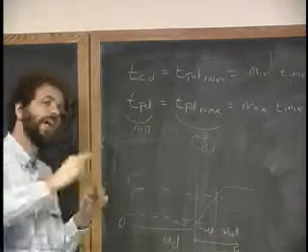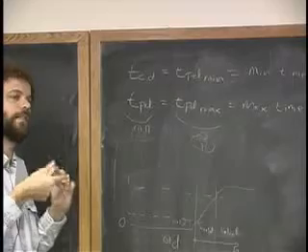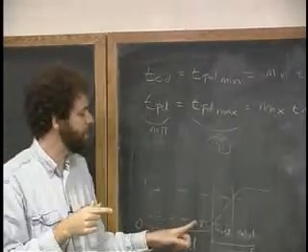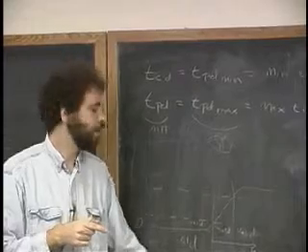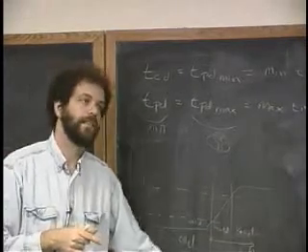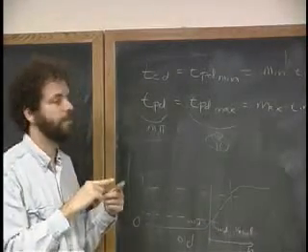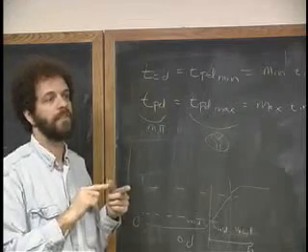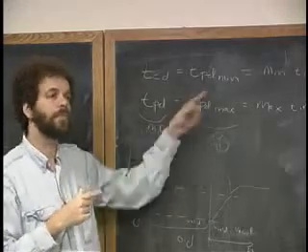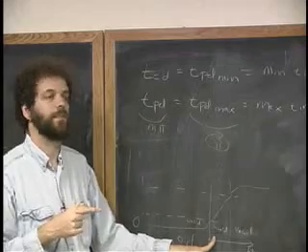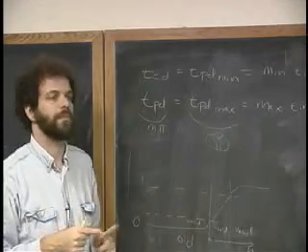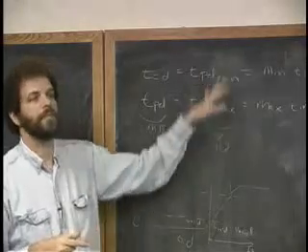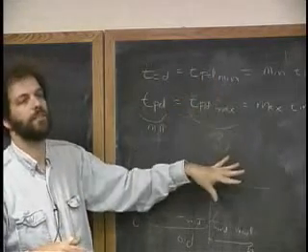So there's sort of two concepts being mixed together here at the same time. One having to do with whether we're measuring time from invalid in to invalid out, or from valid in to valid out, and whether we're doing a measure of min or max. And it turns out that we only care about the minimum for the invalid inputs, and we only care about the maximum for the valid inputs. And that's why they're paired up in this way. There aren't 4 possible things to measure, there are only 2.